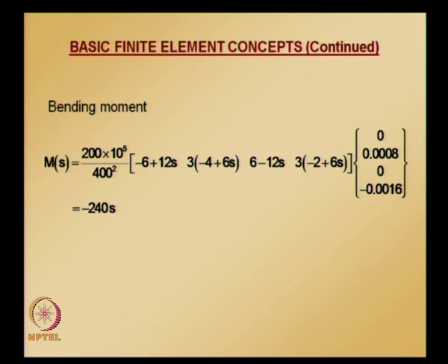Similarly, bending moment can be obtained by using the nodal values in this manner. By substituting S equal to 0 we get the value of moment at the left hand node, and by substituting S equal to 1 we get the value of moment at node 2, or the second node of element 1.